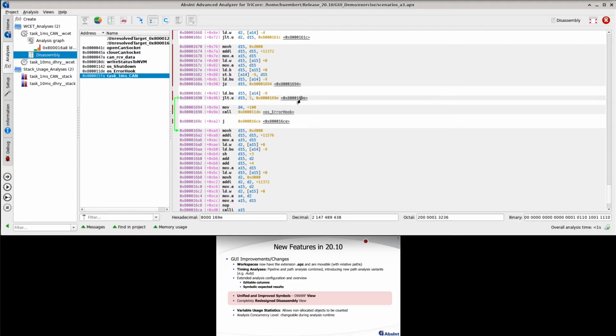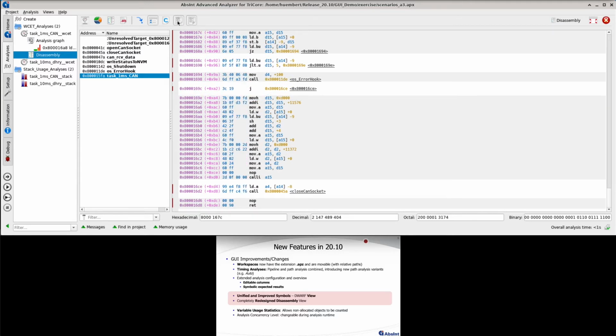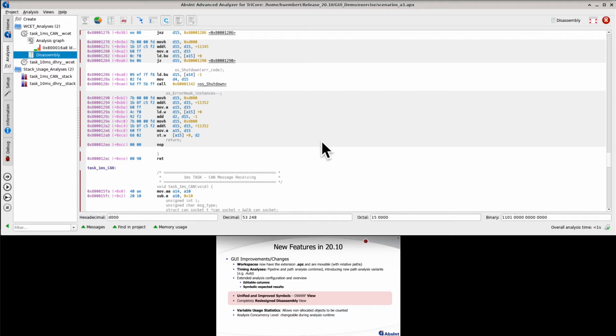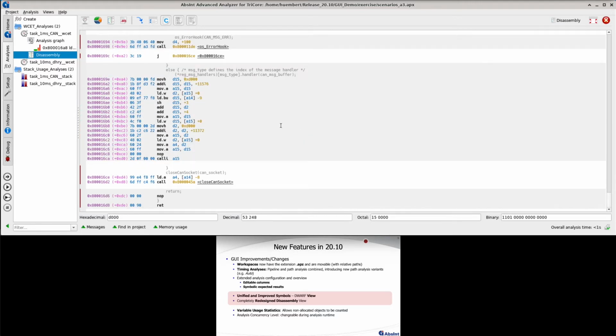You can follow jumps to that instruction, and there's also a possibility to display the opcode now by some toolbar option, and of course the intermixed source code can also be displayed in the disassembly. This function list can also be switched off if you like to have a better overview of the assembly. So this has also been redesigned and improved.